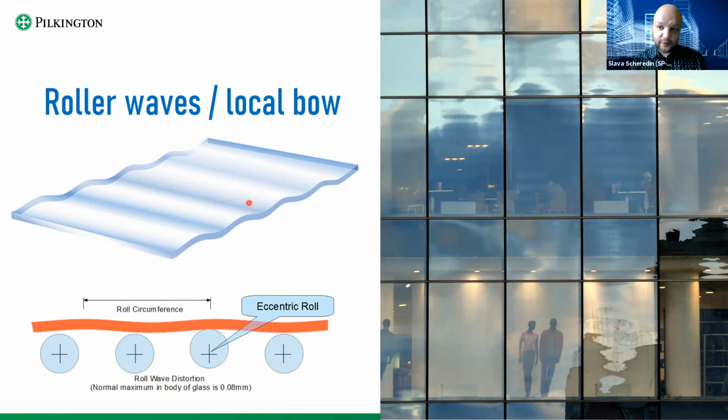That is because 4mm is a very thin glass, and it is very difficult to be properly tempered without roller waves. 6mm glass is way better. So for outside, if you want it to look good, and if your glass is dark or reflective, go for 6mm tempered glass, not 4mm tempered. If you're not tempering it, okay, no problem.